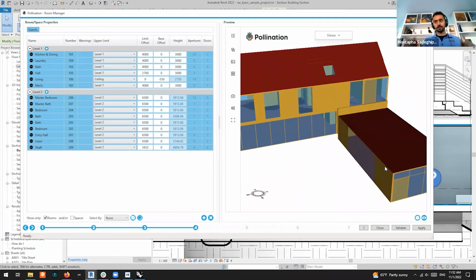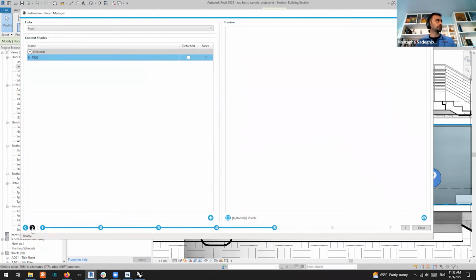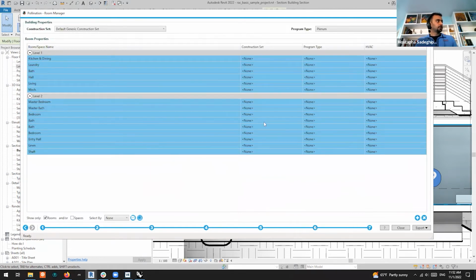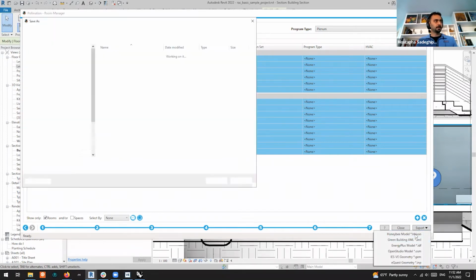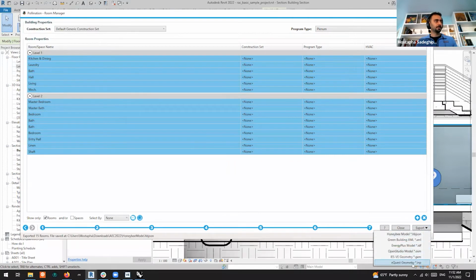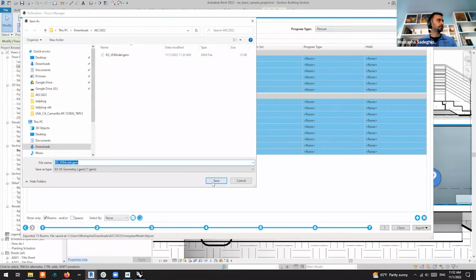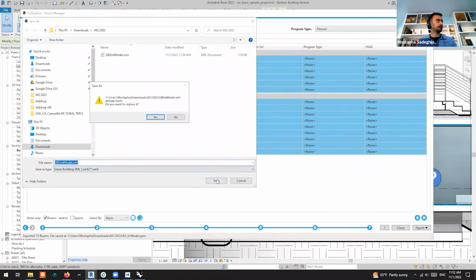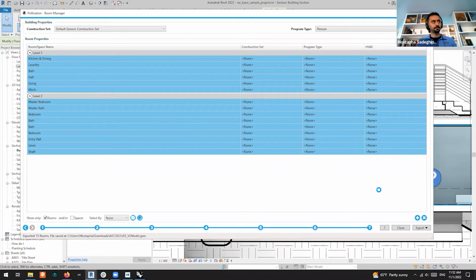So we're at 11:52. We have 8 more minutes to go. So let me go to export everything next. Now I'm going to select everything and export them to the 3 files. Let me do HB.json, overwriting the one that we had. Let me export to gem and save it. And let me export the green building GBXML and save it. So I saved all 3 of them.